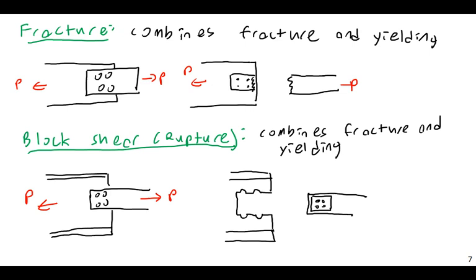Any piece of steel, before it can fracture, has to yield. Even something like glass will yield a tiny, tiny bit before it fractures. Very brittle materials just yield a very, very tiny amount before they fracture. But when we look at connecting elements, we're not going to consider the yielding limit state simply because they're so stubby that, yes, they yield, but the actual measurement of that yielding in inches is so small that it's not going to cause failure or cracks in drywall or something like that.